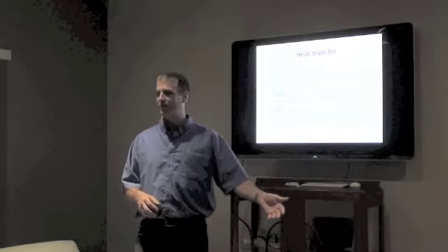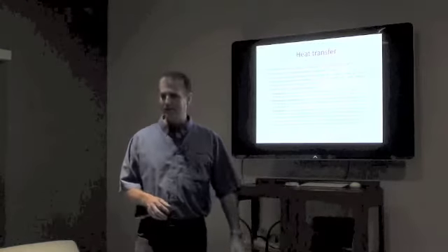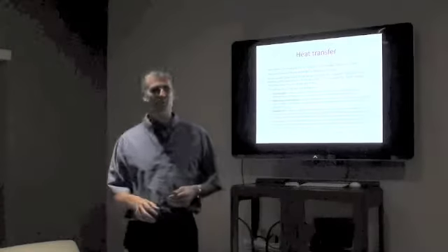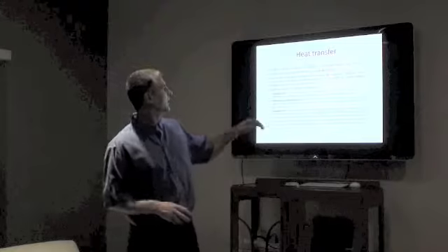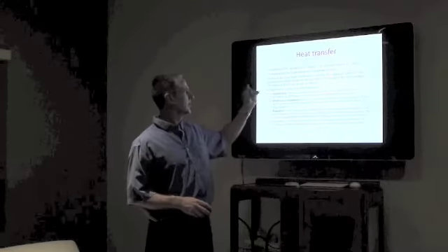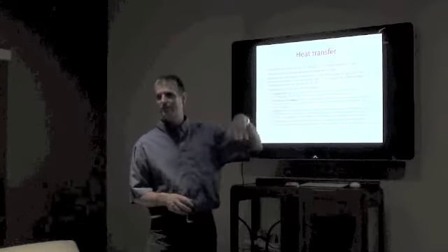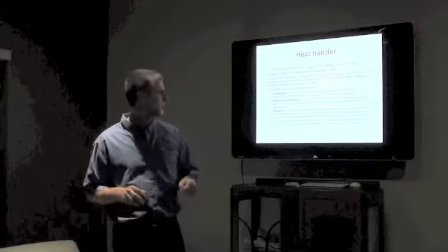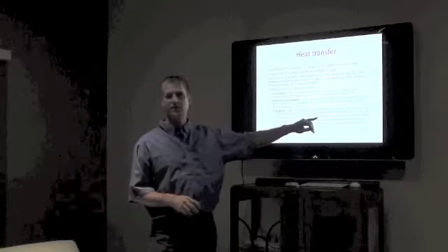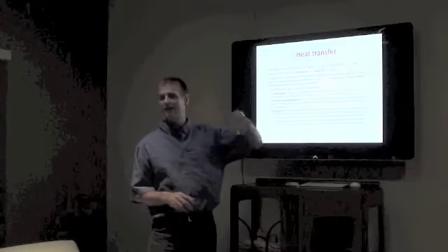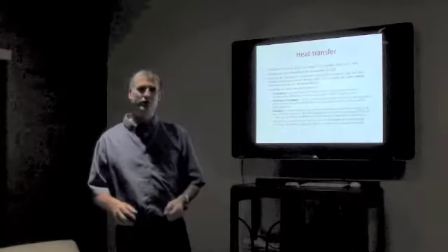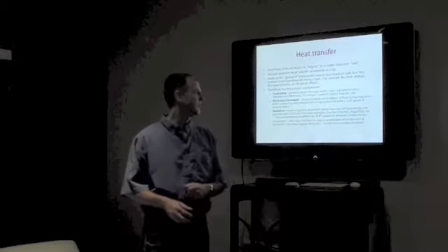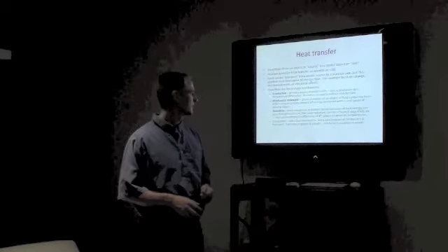Typically, dark objects are better at absorbing that heat, or radiating heat back to me if they're warmer than I am. For conduction, I should have mentioned that the rate of heat transfer is proportional to the temperature difference between two objects. Whereas for radiation, it's a bit more complicated. If you take the absolute temperature of the two objects to the power of 4, that determines the rate of heat transfer between the two objects.